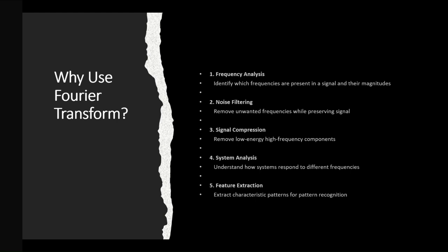Why use Fourier transform? First and foremost is frequency analysis. If you have a signal, we have to identify what are the frequency components available in the signal. Always, we cannot say that a single frequency component is there. Along with the actual frequency that is to be transmitted or processed, unwanted noise signals will also be available. So, we can analyze that using frequency analysis. For that, the Fourier transform is needed.